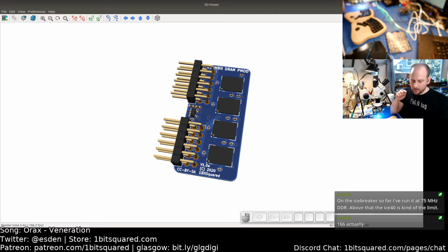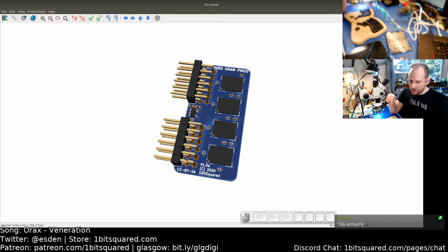On the Icebreaker, we can switch the power supply for the I/O banks fairly easily, but changing the power supply on the Pmods, so these pins, is much harder. So instead of futzing around and rewiring the Pmods, I decided to just put the 1.8 volt voltage regulator on the Pmod that takes the 3.3 volts and steps it down to 1.8.